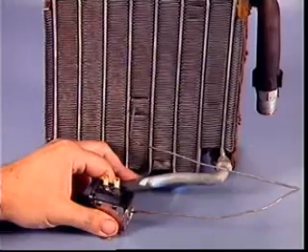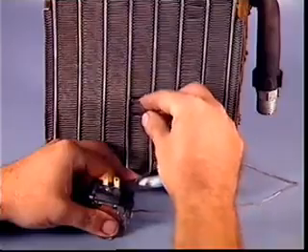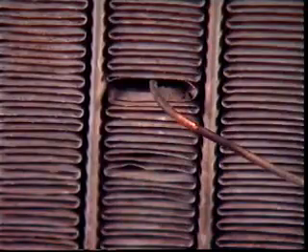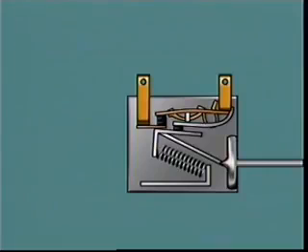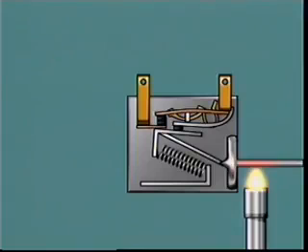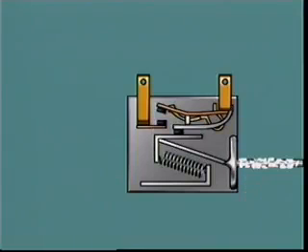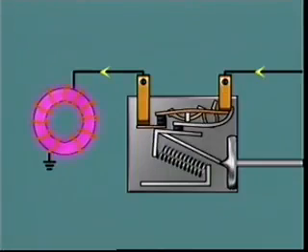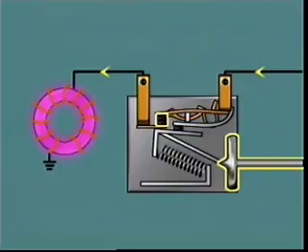The bellows type has a capillary tube that is placed about 25 millimeters into the evaporator core so that it contacts the fins. The capillary tube and bellows are sealed and filled with a temperature-sensitive fluid, which expands and contracts with temperature changes. This increases or decreases the pressure in the bellows. The bellows is positioned to open and close a set of contacts which form part of the electrical circuit to the compressor clutch. Springs connected between the bellows contact frame and the thermostat housing try to keep the contacts open. Pressure in the bellows tries to force the contacts closed.